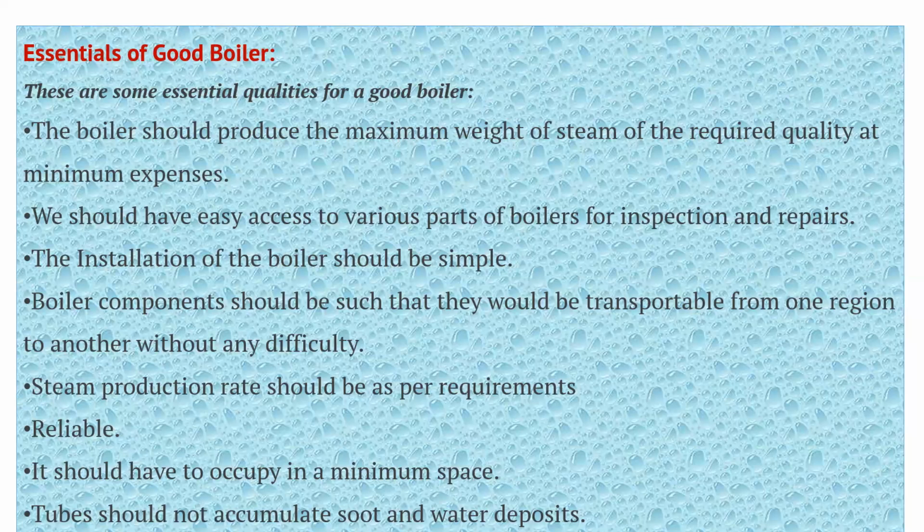And steam production rate should be as per your requirements and necessity, and the reliability. Reliability will come as a very big discussion. Reliability means basically we are correlating with the quality, right? And it should occupy a minimum space. That means, as I told you earlier, when the floor space is limited we take some conditions, and even if you have more space availability initially, the boiler should not occupy larger space so that you can utilize the extra space for some other item.